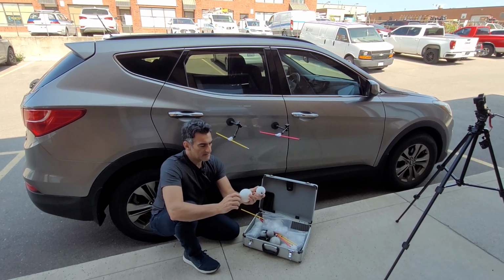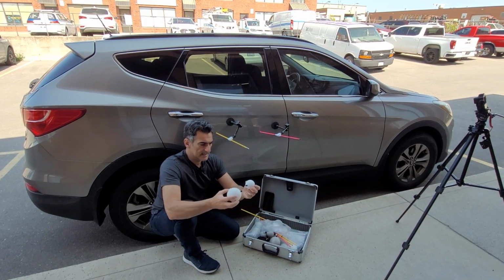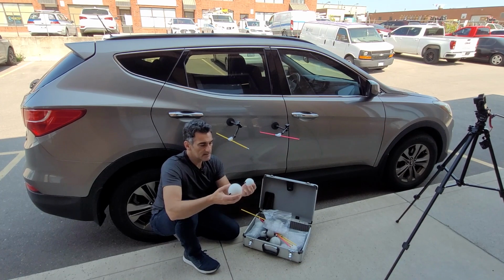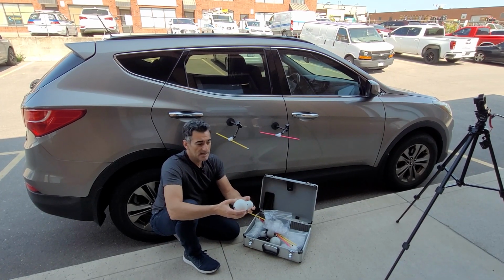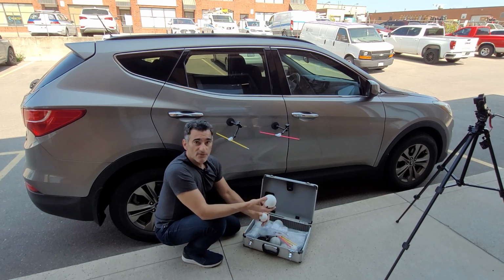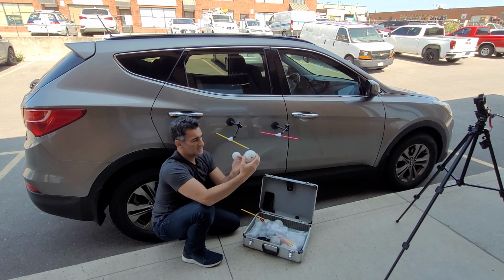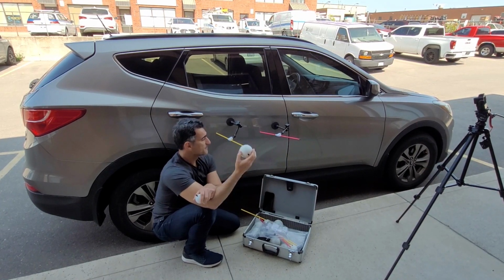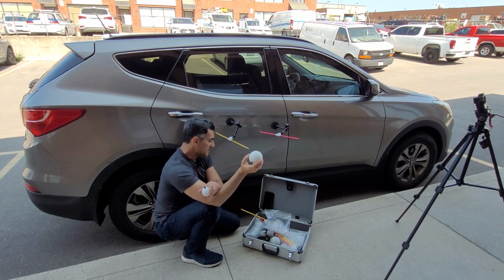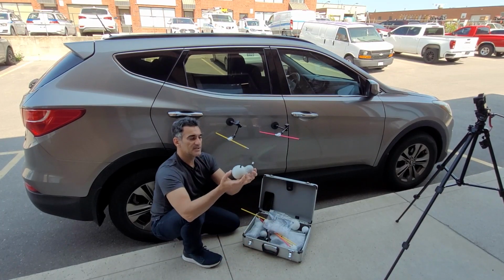Now, normally with a terrestrial laser scanner, these would work absolutely fine. You can use these and you just put them on the rods. For all the testing that's been done, these prove to be fairly beneficial. Spheres are very commonly used in laser scanning for registration for a number of different things. Using these targets gives you a greater surface area and you tend to get a great result. So you can use these with Recon 3D. However, there's a little twist to that, and that is that we have spheres with some texture on them.